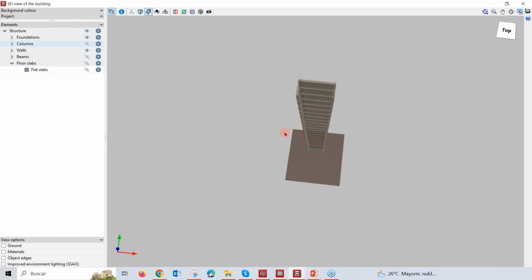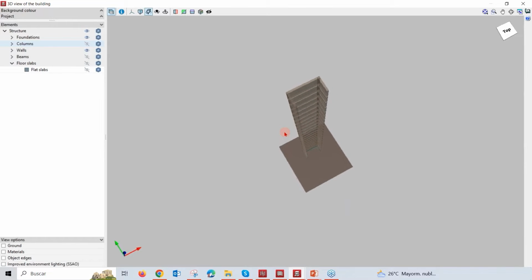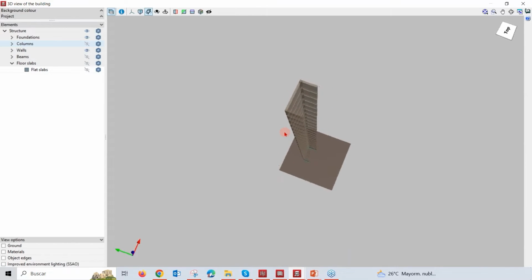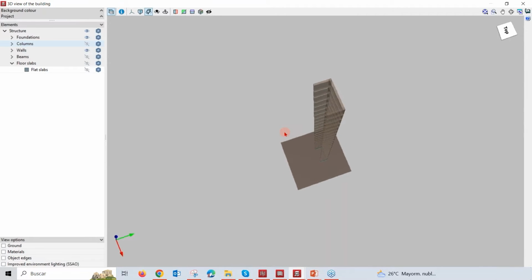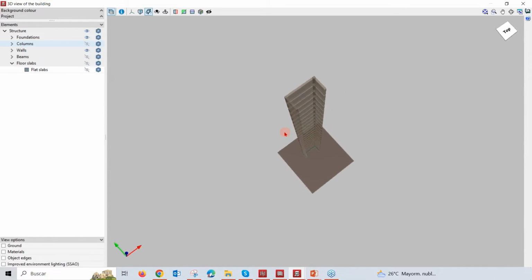Yes. From here in CYPECAD, we also define this structure as a shear wall. We are going to export again back to the BIM environment and use another software called Open BIM Shear Walls. From that software, we are going to get the reinforcement, and then we can use another software to get detailing drawings and so on. Okay, that's the process more or less.